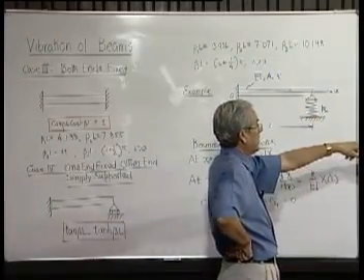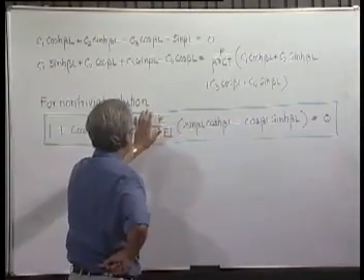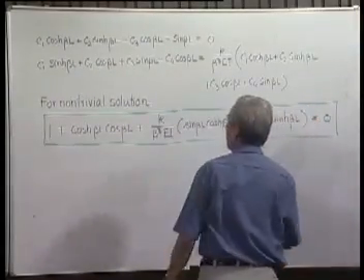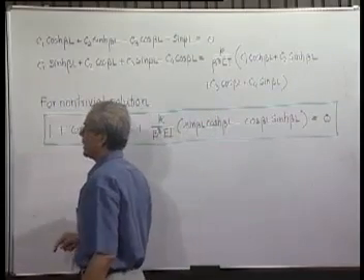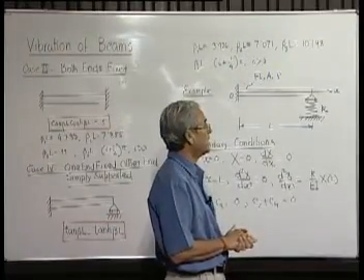So this must go to the cantilever beam. You can see when k is 0, this whole part goes and cosine beta L into cosine hyperbolic beta L must be equal to minus 1. That is the condition for a cantilever beam we have already seen.